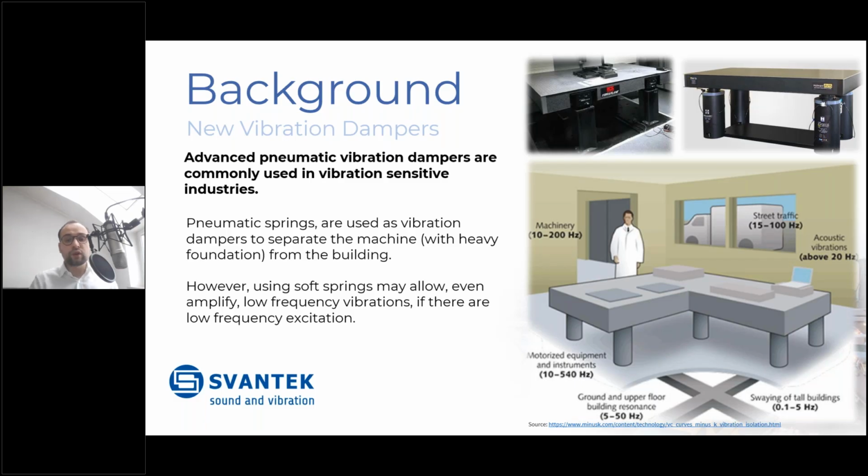So if you were working in an environment where there were a lot of heavy equipment, machinery, street traffic, you name it, you could find yourself in a very high vibrating environment, not allowing you to perform these very fine operations that we talked about. However, with the development of advanced pneumatic vibration dampers, we're able to create things such as tables that were completely separated, decoupled by vibration from the area.